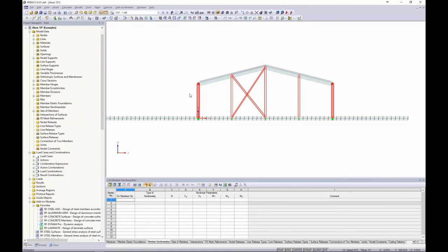Now, geometric imperfections really are to account for a column out of plumbness. There are some other stipulations that you can maybe add in, like precamber, which we'll see in just a minute, but for today we're really concerned with column out of plumbness in terms of geometric imperfections.